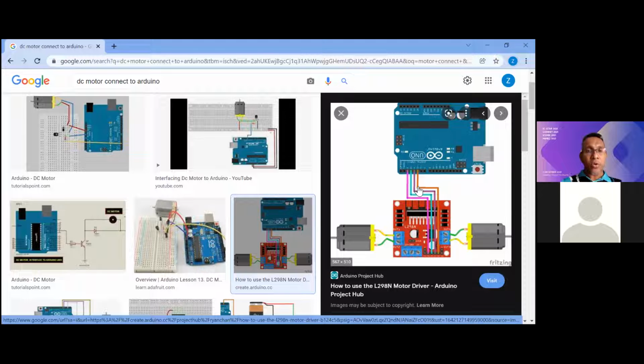So for some motors you need to design an electrical circuit by your own, to interpret the PWM to the Arduino. But nowadays, I think no problem. You can find they already give this solution and then directly connect to the Arduino. But some motors also already do it inside. So you need to read the manual for the motor spec also, because they have voltage.